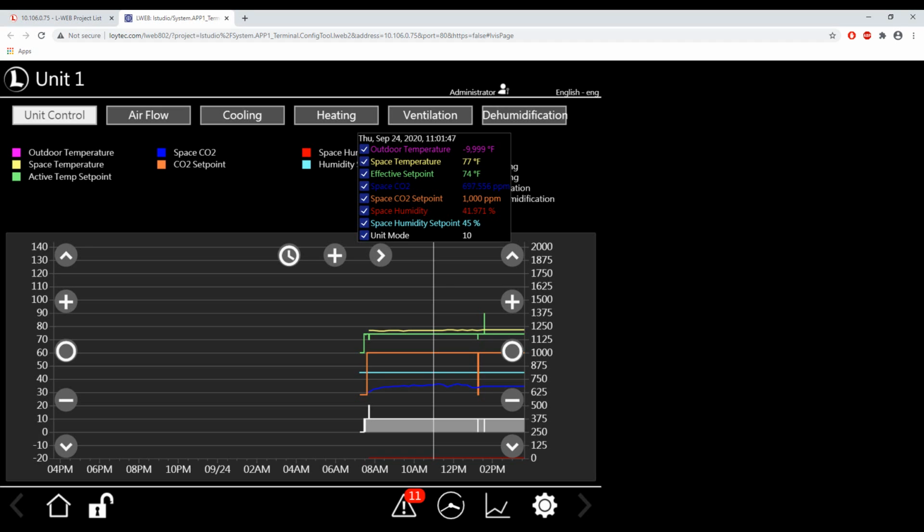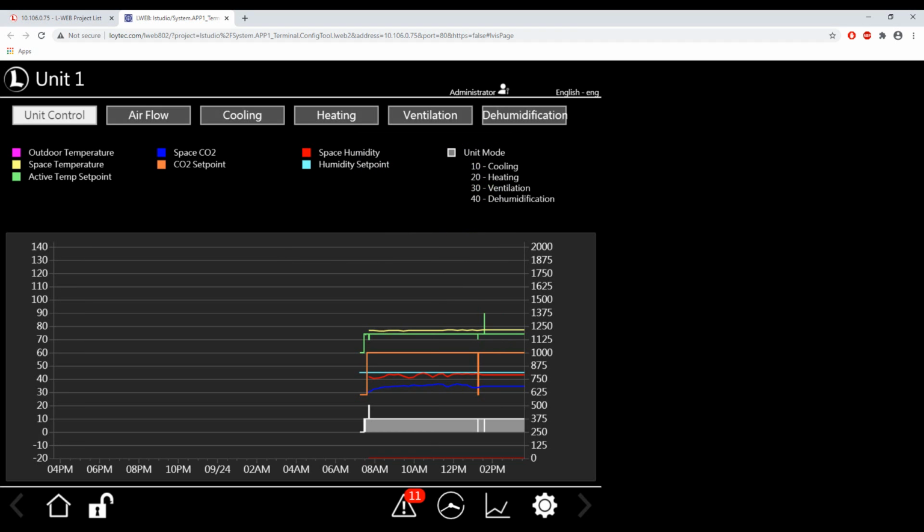Once you have finished configuring the terminal application, it is a good idea to create a new backup of the controller. This backup can then be used to restore not just the configuration of the device, but also port settings and network settings to the controller should there ever be a device failure.